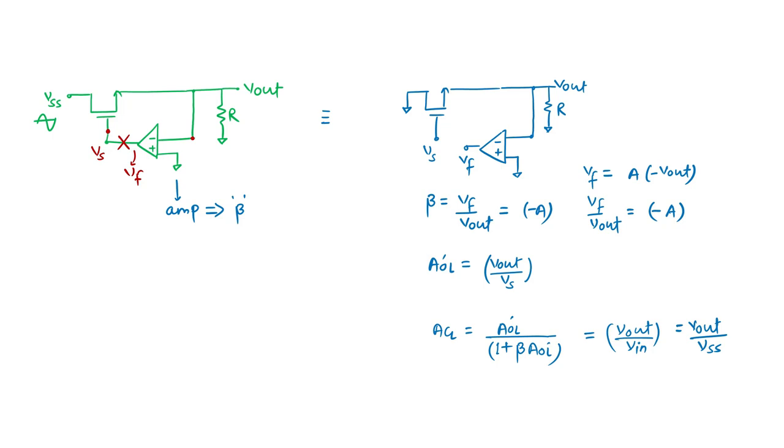So we have seen the feedback factor. VS is not mandatory here, because VS is only required when we calculate the loop gain. But yes, we can use the loop gain also to calculate the closed loop gain. That is not a problem. And directly, the closed loop system gain can also be calculated as 1 upon beta times loop gain divided by 1 plus loop gain. This is also a valid way of calculating the closed loop gain.